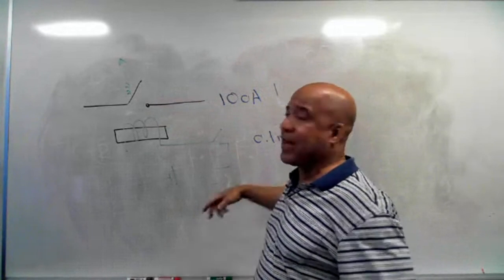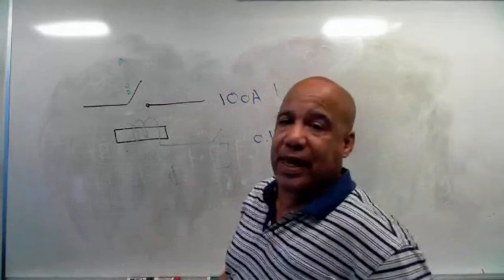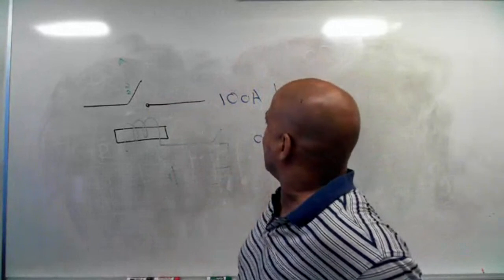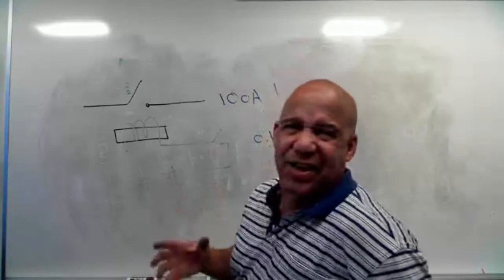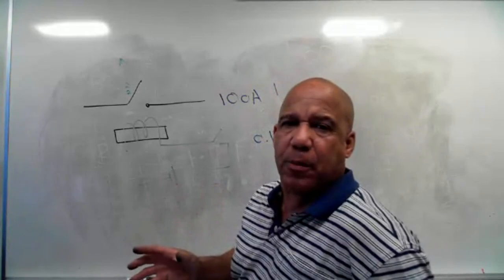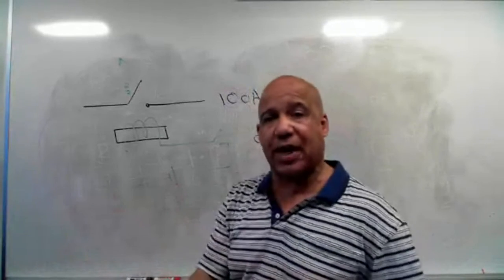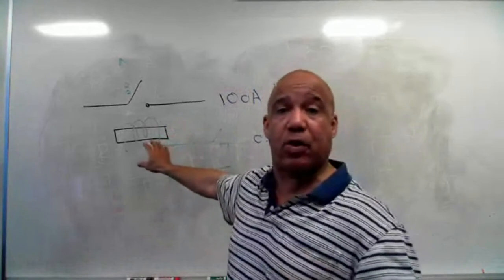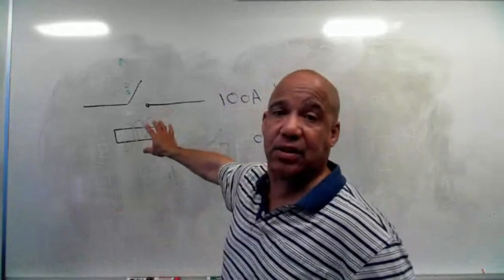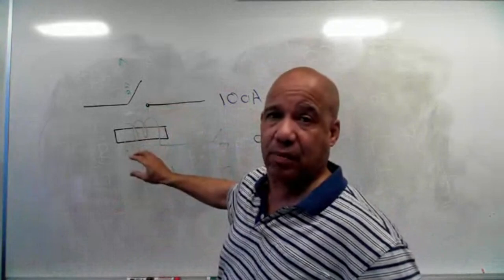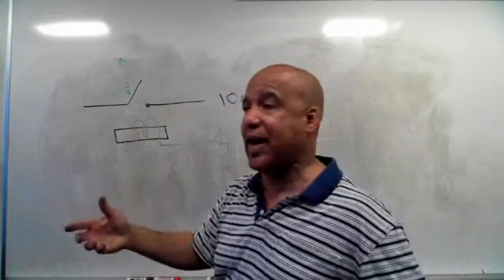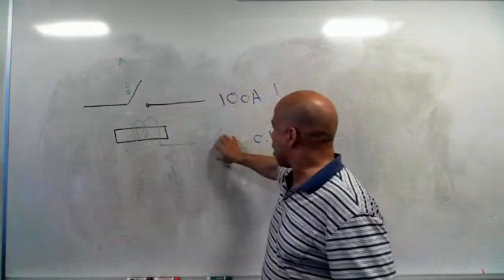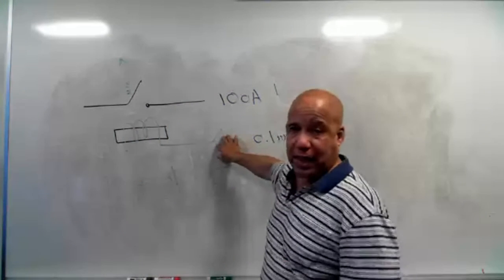Anybody have any questions for me or comments? Okay, well, when you guys do your research, he'll talk about relays. And again, I'll say a little bit more about this because relays are not so much used now for logic purposes. In the old way of doing it, we used a lot of relays. But it really helps to understand what the software and the computer's doing if you understand relay logic. So relay logic is what we're talking about. Instead of using switches, we're using relays. That way we can allow currents to control our logic circuit.